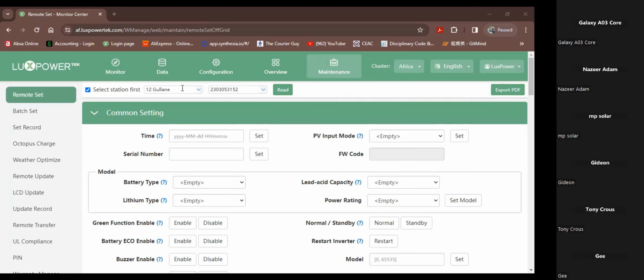Okay, you must remember that we do issue two voltages. One is the maximum MPPT voltage range, and the other one is the operating voltage range. Typically, if you look at the specifications of a panel, it will have an open circuit voltage, the VOC. It could be 48 volts, it could be 50 volts, but let's work on a 48 volt VOC. Open circuit means that the circuit is not closed. In other words, there is no load across the circuit, okay?